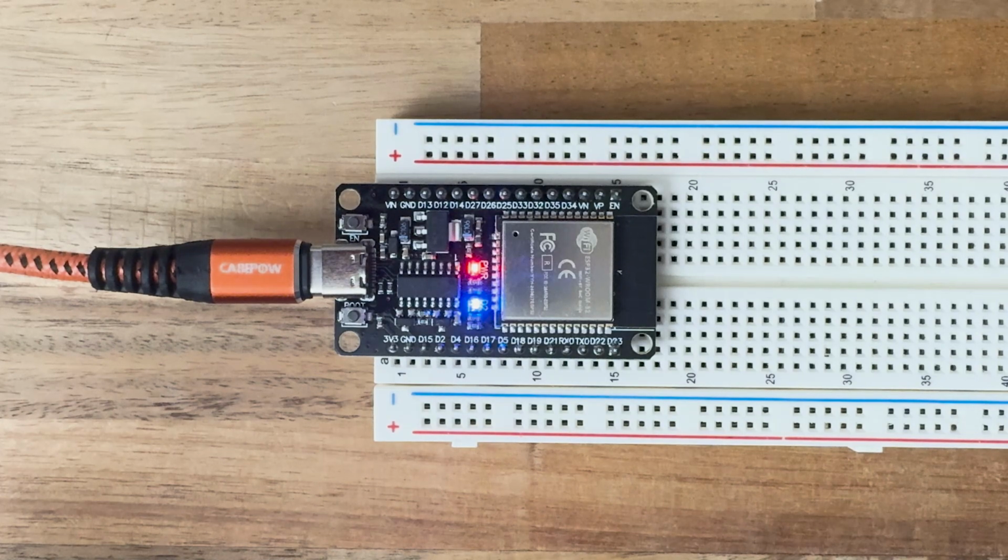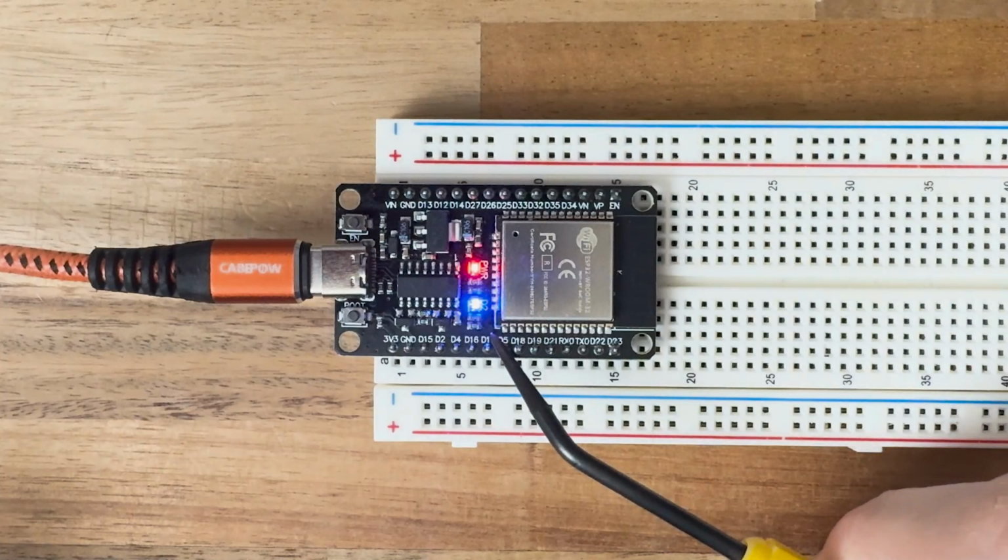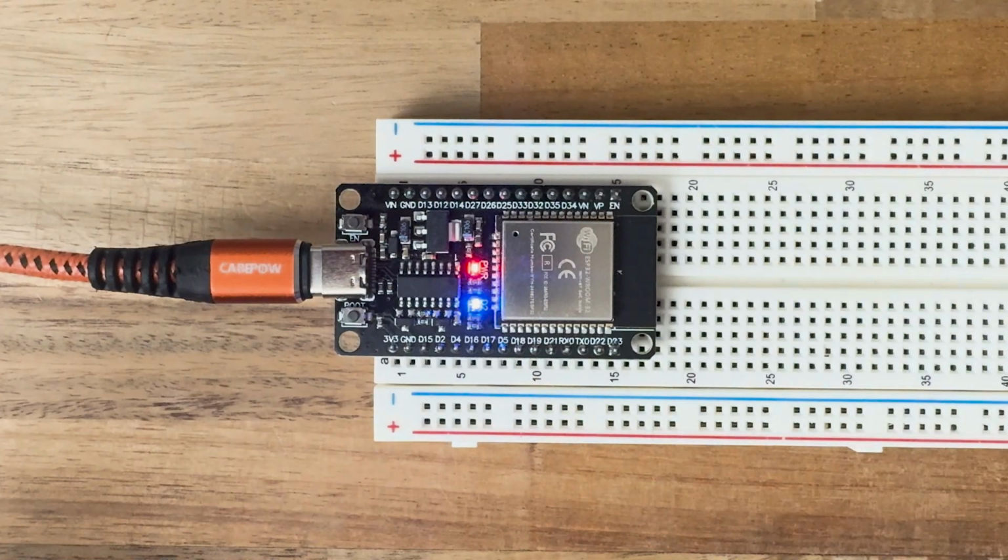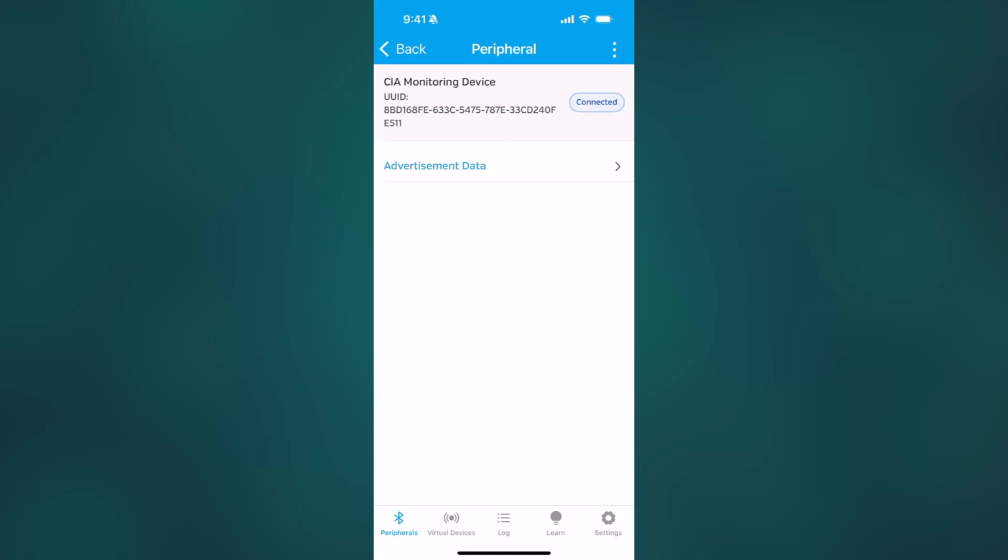Okay, so now I've connected to this device, and you'll notice that the LED on my ESP32 turned on. Like, that's pretty sweet, right? Because that was that My Server Callback class, right? The callback on connect got called, and that LED turned on. Now, again, we don't really have any advertisement data in here, right? We haven't specified anything yet. This is all part of what we'll be doing when we start adding services and that kind of stuff.